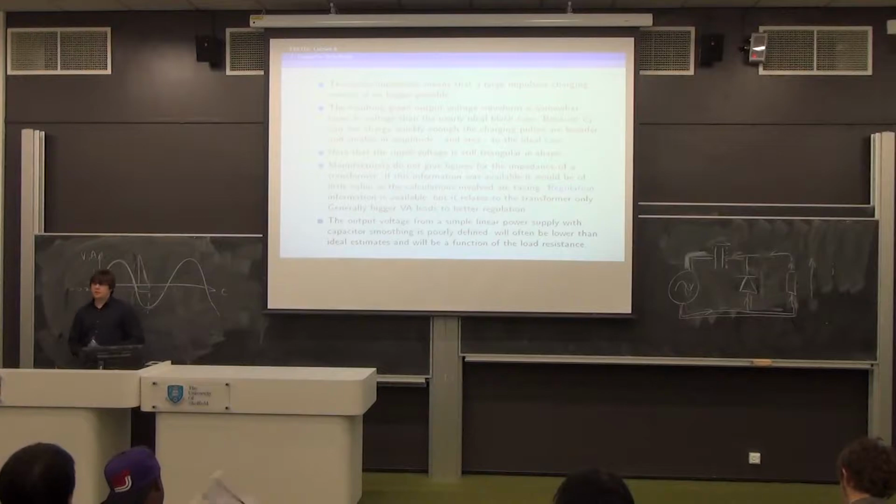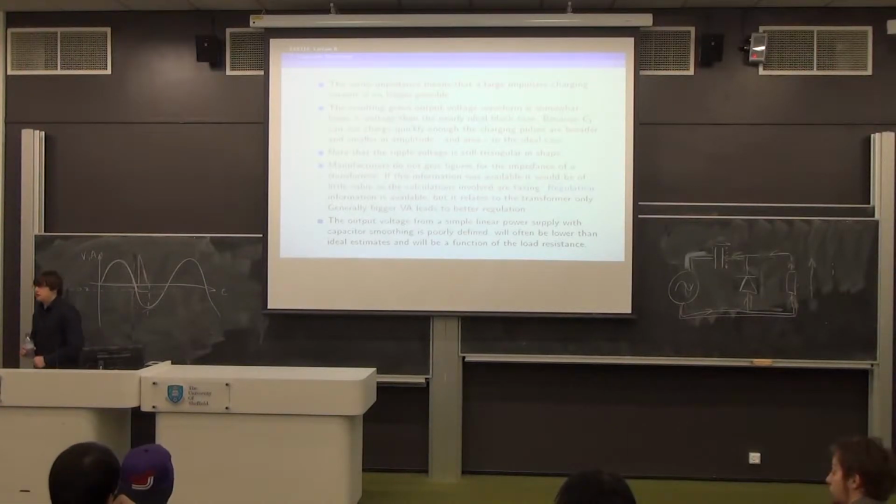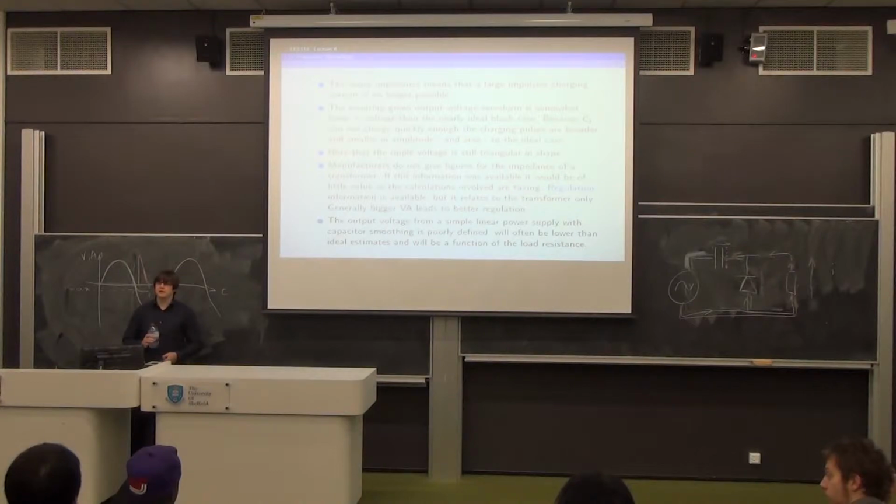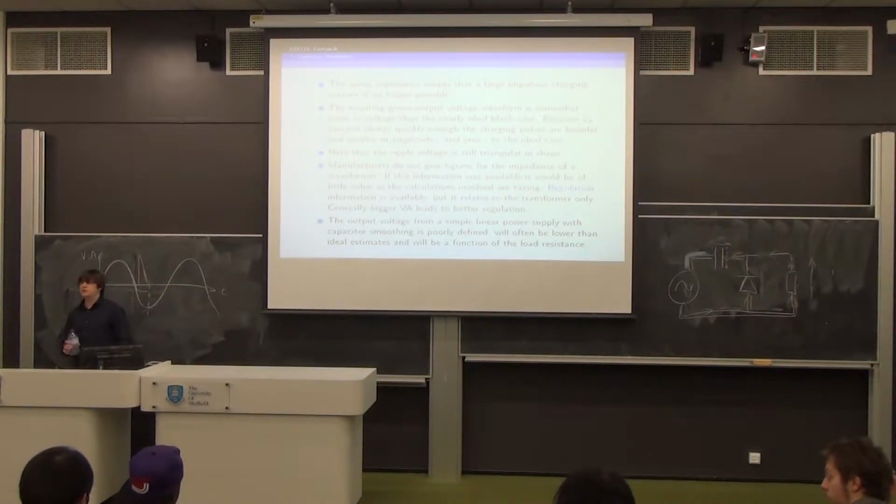If you are buying a transformer, you'll find that there's something called regulation, which is not regulation in the sense that I will discuss it in this course. It is to do with how much variation there is in output voltages for certain input voltages. Generally speaking, the bigger the transformer, the better the regulation is. If you were buying a couple hundred VA transformer, you'd expect about 5%. If you want to know what that's all about, go and look it up on the internet, or in a book, even better.